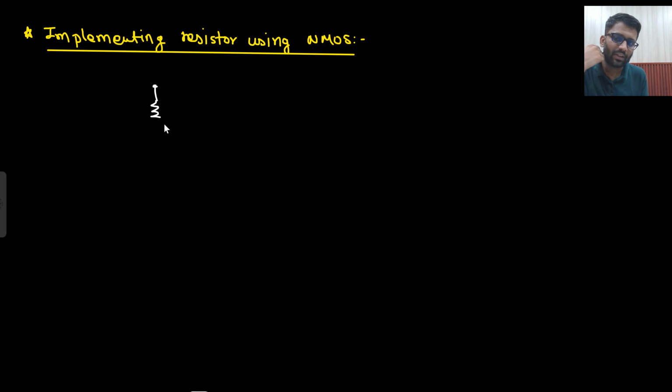So actually we can never use resistor R there, because resistor R will depend on temperature. These kinds of resistors will highly depend on temperature, and they can change very quickly with respect to temperature on your IC. So you will make these resistors from MOS only. You can make this resistor from PMOS. Okay, so resistance R is there, this is your VDD supply, resistance R is there, and then there will be a network. These kinds of things we have already seen in analog electronics, how to make these resistors.